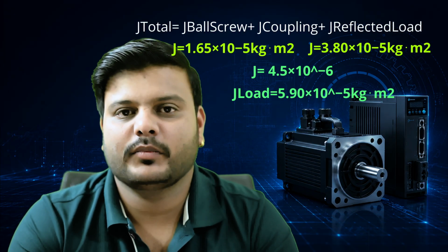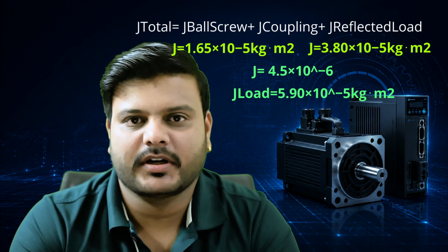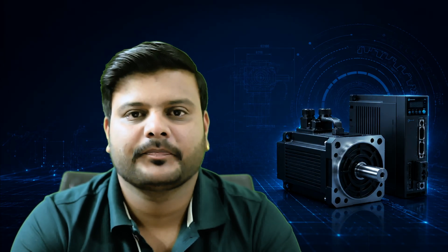And now it's time to calculate the servo rotor inertia. Every servo motor has its own inertia, and this value is published in the manufacturer's catalog. So we don't calculate it now. We will take this value later from the manufacturer's catalog when we select a servo motor. We know the inertia ratio is equal to total load inertia divided by motor inertia, and we will calculate this after selecting a specific servo motor from the manufacturer's catalog.